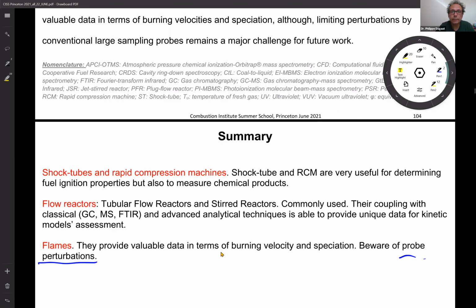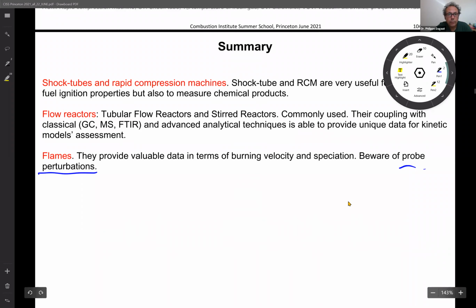I would like to spend more time answering questions. I see I have 2 questions here, but I am ready to carry on forward. Okay, so can the laminar flame velocity be calculated in RCEM using the shadowgraph method? Yes. How can one remove the effect of flame stretching? Well, there are different methods which are described in the literature, where you extrapolate to the condition where stretch is 0. There are linear and non-linear methods.